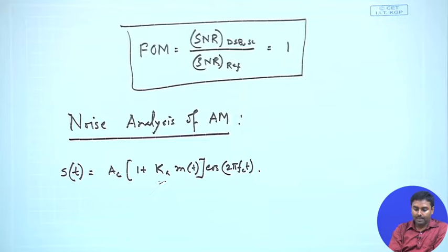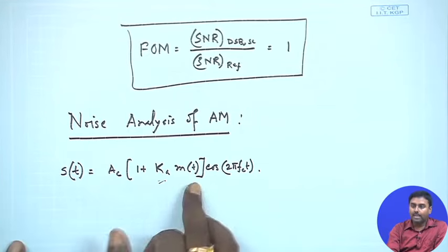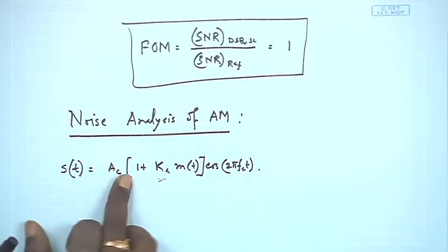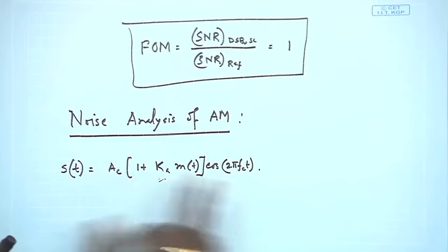Basically, what we do is we add a DC to the signal and then modulate, or do a DSB-SC. Otherwise, you can see it as the DSB-SC plus the carrier part. If you just multiply this, that should be the carrier part. So, the carrier has also been added over here. So, this is our modulation. Corresponding demodulation, the demodulation of AM was easier. What we did is something like this.